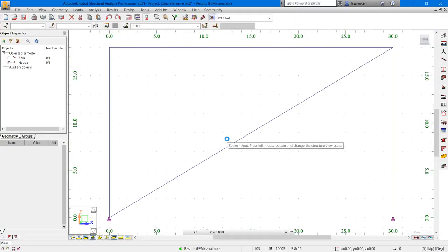In this video, you will learn the basics of concrete design on a concrete strap beam or ground beam. This beam connects two pad foundations, which in turn supports the two steel columns and the steel frame above. Let's begin by modelling the strap beam between the two pad foundations. On the Structure Model toolbar, go ahead and select the bar command.